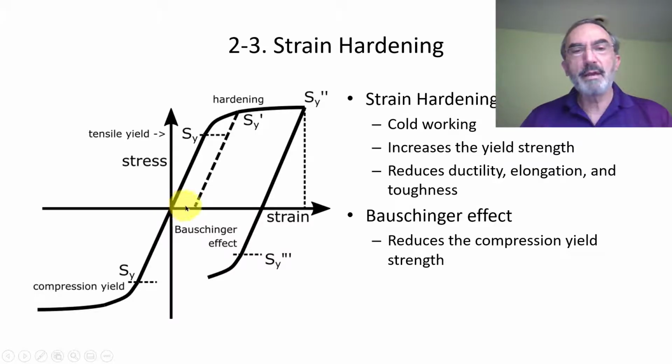Yes? Okay, so you unload it here, and now you say, oh, I want to load the structure back up. Now you load on this line, same modulus of elasticity, and we're going on this line. Everybody understand that? If I went up here, go there, unload, stay there, you don't go anywhere. So now you load up, and you reach this value, which before was a big deal, but nothing happened, it looks linear, and I can go all the way to this S sub y prime, because the material is said to have hardened.